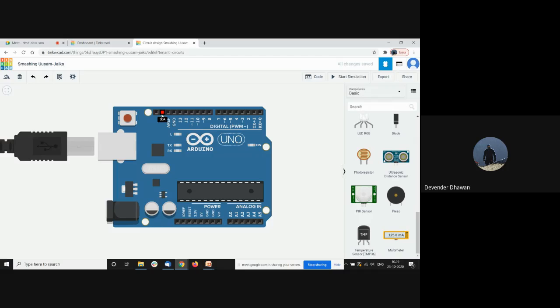Okay. Then we have multiple IO pins also available. Like you can see in this case, these are like power pins. These are analog input. Okay, so mind it that these are only input pins. We have 6 input pins, analog inputs. So they cannot be used as output also, but only input. But these analog pins can be used as digital input and output also. That is up to us.